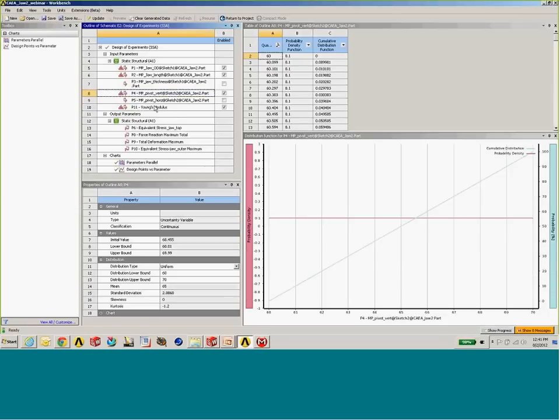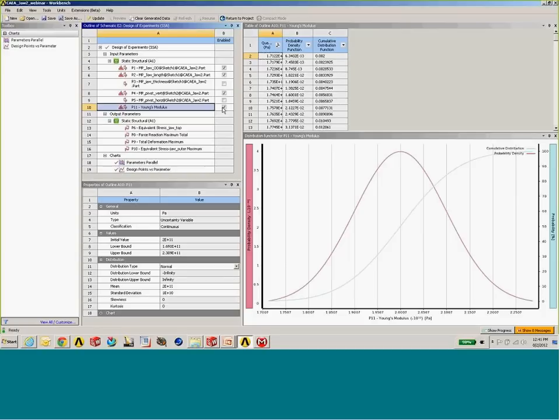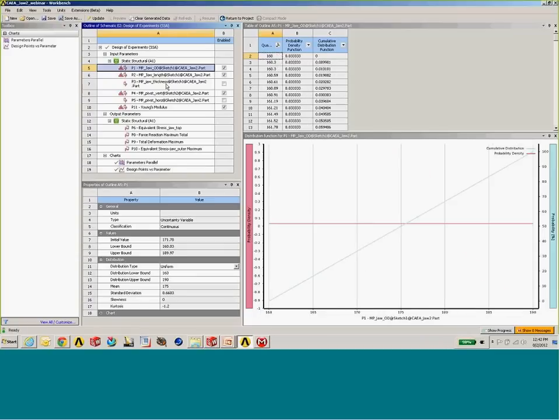So, for instance, if I happen to have some information on my Young's modulus that represents something like a normal distribution or a bell curve, I can assign the input or the probability based on the mean and the standard deviation to give me a distribution of that sort from my Young's modulus. And if it's something like a dimensional value, you may only know the min and the max value for that dimension. So you may use something like a uniform distribution. Or if you have additional information like a common point, you could use a triangular distribution.